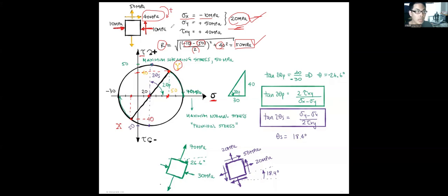If the rotation is in the other direction, we define it as minus. So we can figure out the stress condition at the y point and the x point, and we just connect these two points to get the stress conditions x and y on this Mohr circle.